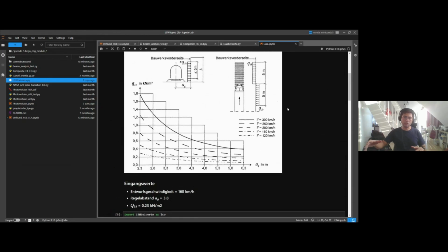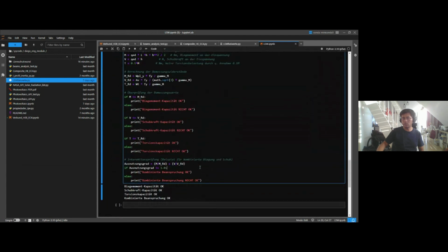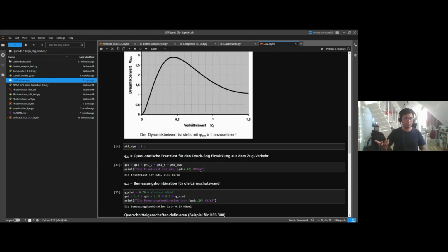We took this proof of concept. We just took the information that the sound fence designer gave us about the distances and the height. We turned that into a TXT file with basically 2 columns. We just ran the script and for each of the rows in our TXT file, did the verification that our HB profile is always under the ratio of 1, and as long as it is under 1, we could use this profile for 80%, 90% of the project. We use the same profiles that we somehow estimated with this tool.